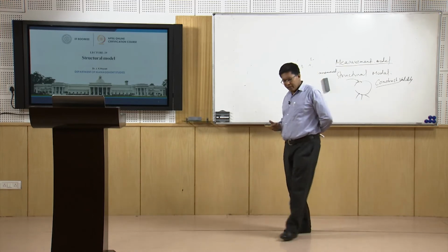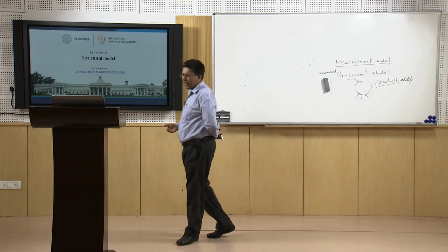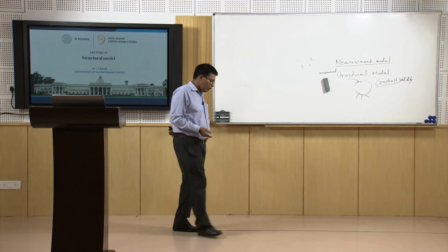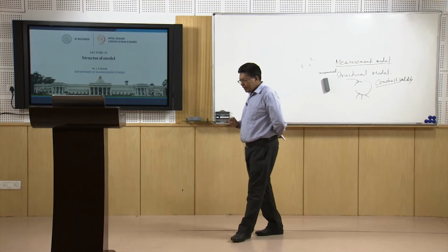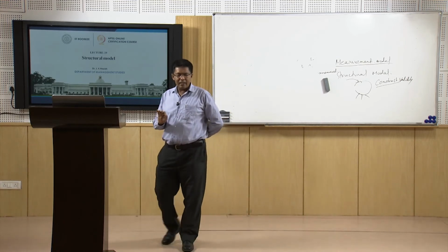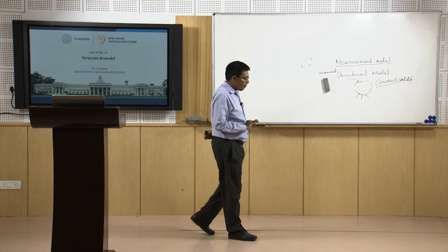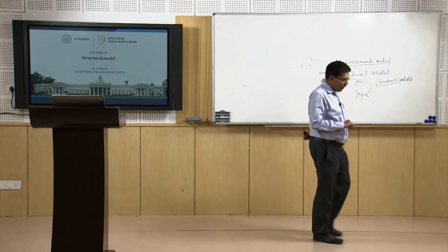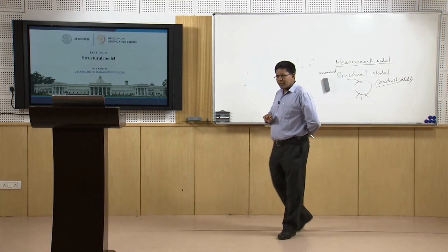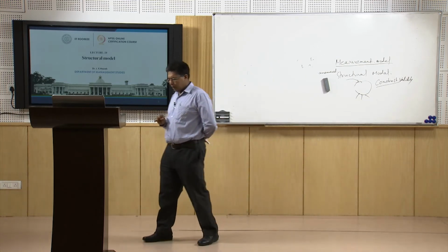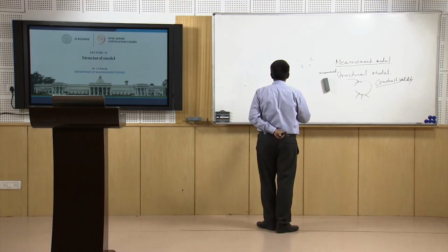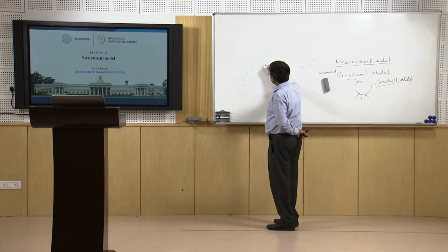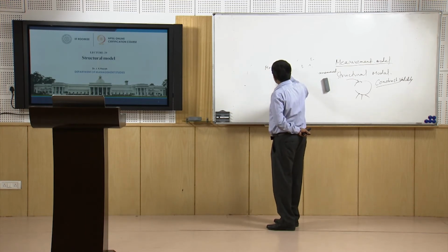that is to check for the fitness indices. Now, in the fitness indices, suppose you have checked and they are all coming 0.9 and above. So, that means the model is now clear, it is a fit model, right, there is no problem with it. But in case there is a problem, let us say a poor model fitness is showing, then Amos has a facility to improve the model. Amos is the software which you use for Lisrel, and Amos being a very popular software. To improve the model, you can do one thing, you can use the modification indices.